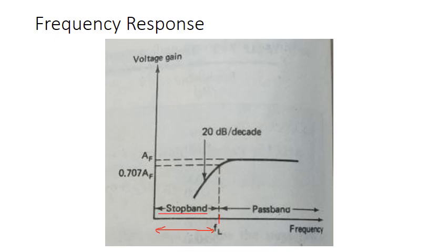Frequency beyond this FL is passed, which forms the pass band. The roll off rate, as we have already seen for the first order filter, is 20 dB per decade. For every 10 times rise in the frequency, the gain falls at the rate of 20 dB. For higher order filters, this comes closer to the ideal.